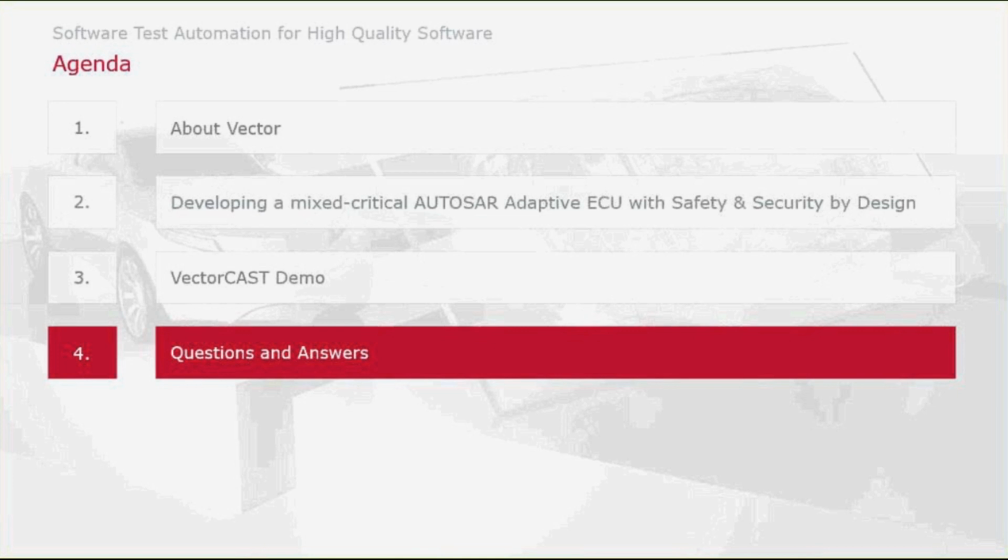You can have multiple different scheduling schemes between which you can choose and switch back and forth, so there's some flexibility there. We don't do any dynamic scheduling. It's, as I said, based on time partitions, and within the time partitions, there's a priority scheme going on. So yes, if one of your resources is starving, then it's an architectural mistake by not providing enough computation time in the scheduling scheme that you have to define.